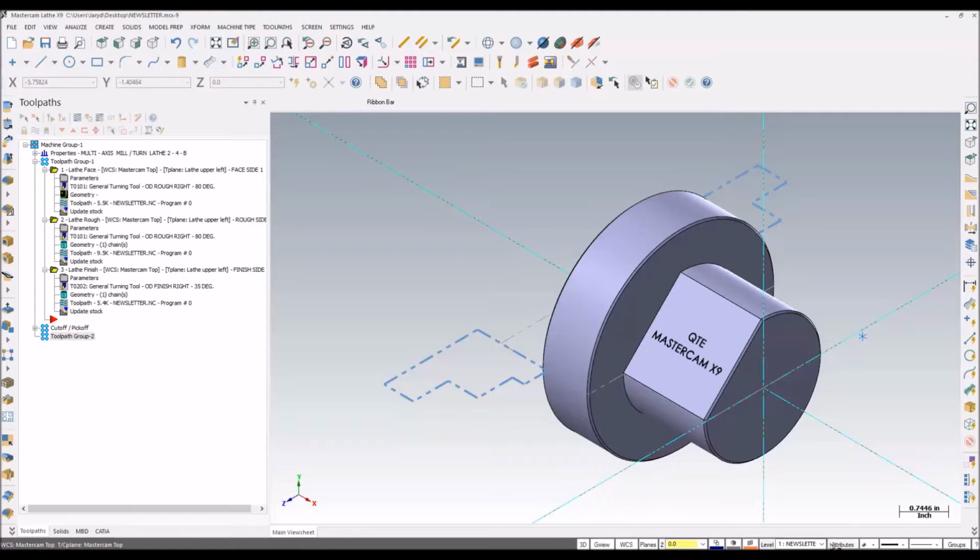In this video, we'll discuss how to properly set up tools on a twin spindle lathe with a B-axis. By doing this, we're able to use the same tool for both main and sub-spindle operations without needing to create a copy of the same tool or reorient that tool to do sub-spindle operations. This keeps your tool library neat and orderly, as well as communicates with your post to make sure that the right codes are output for the B-axis.